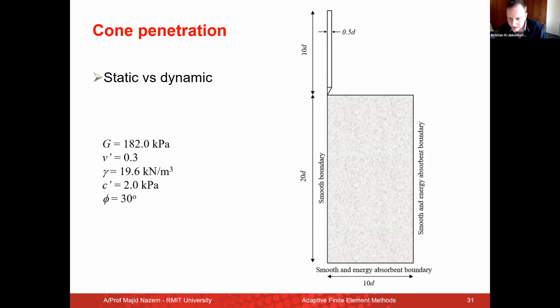I think we are getting to the top of the hour now, but we'll have one more question, and it's on the details as well. What kind of numerical time stepping essentially do you use? Is it implicit or explicit? Implicit, and in almost all dynamic simulations I showed here, we use the generalized alpha method, which has two integration parameters, because the inertia forces and damping forces are measured at two different times between t and t plus delta t. It was actually developed by structural dynamics people, but it's been found to be very efficient for geotechnical problems as well. So generalized alpha method, implicit time integration.